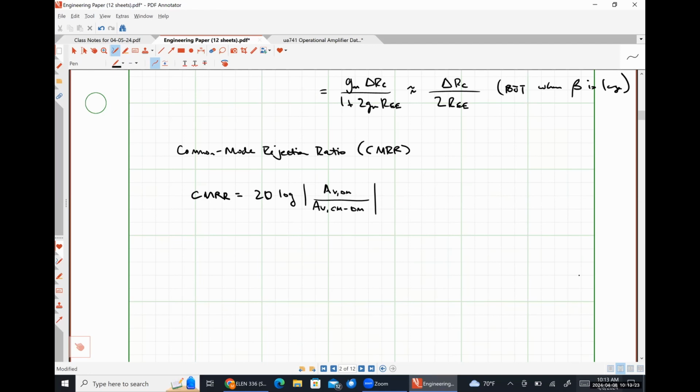One that I have in my head that I'm 99% sure I'm going to give you looks like a cascode amplifier, except that the cascode is formed with an NPN BJT as well as a PNP BJT, which means it doesn't actually behave like a cascode. I would want you to use the short circuit transconductance method to determine the voltage gain of that system. If you can find the short circuit transconductance and then the output resistance, you're good to go. So it's applying what we learned to a circuit that doesn't quite meet the criterion of me being able to just regurgitate the equation I gave to you. Hannah.